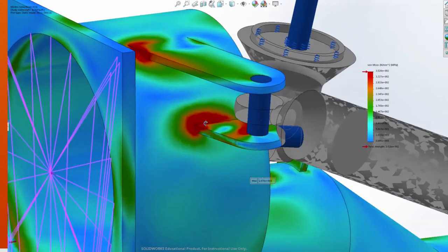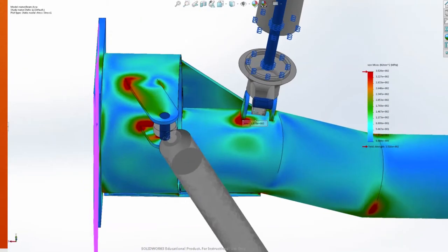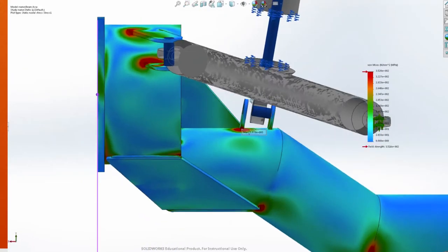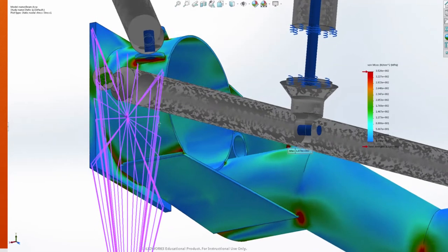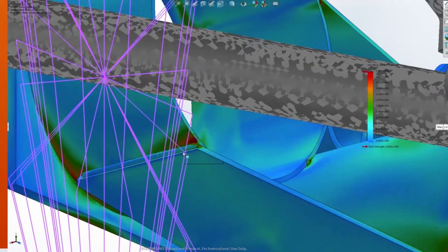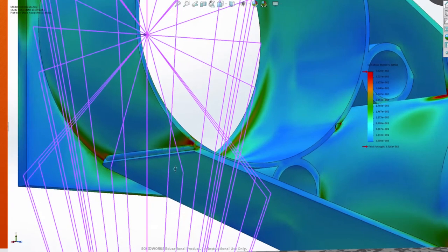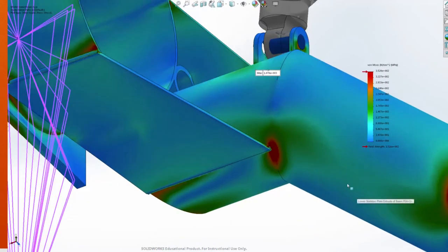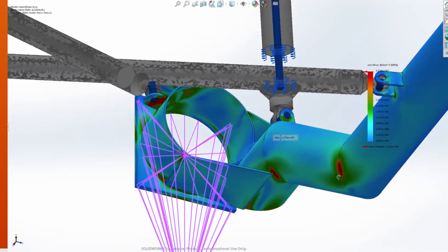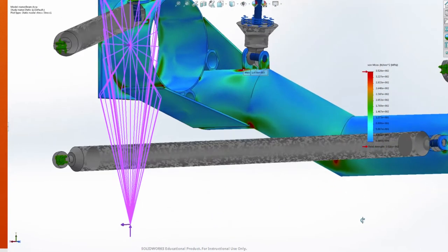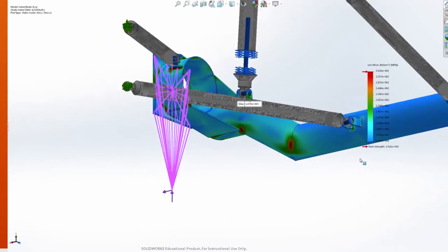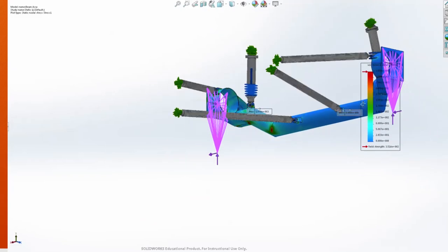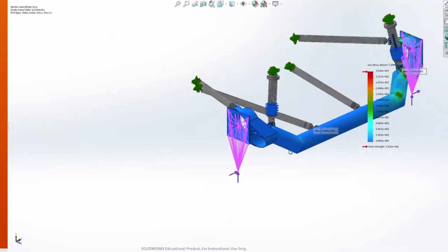So these are fairly thin, and they also do not have the welds added to them. The weld will add more area, so the stress concentration, of course, will reduce due to the same force acting over a larger area. And despite all these stress concentrations that predict failure, the physical beam that was constructed did not ever fail at these points, and there are no signs of failure.